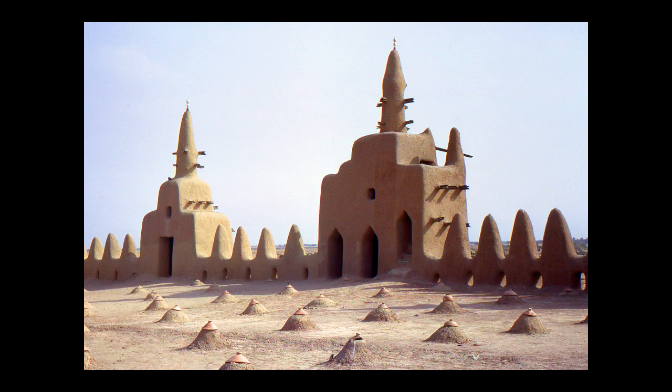The region's hot climate also affected the building's design. The mud bricks absorb heat to keep the interior cool during the day, and then they release the heat at night, keeping the interior warm. Additional roof ventilation also helps to cool the interior of the building, and you can see those ventilation systems here, these mounds with holes in the top that can allow the hot air to escape, or in this photograph, those holes have been covered by small ceramic dishes to keep that warmer air inside.